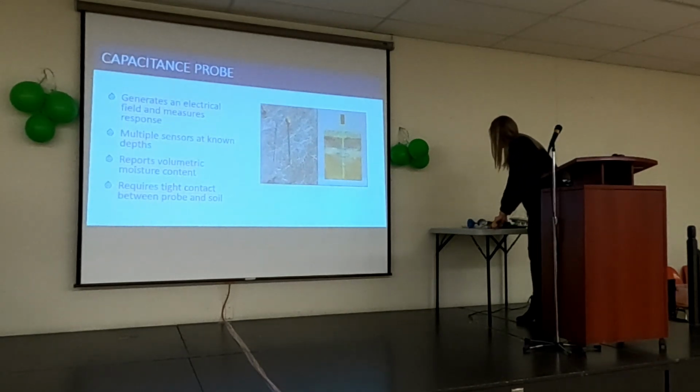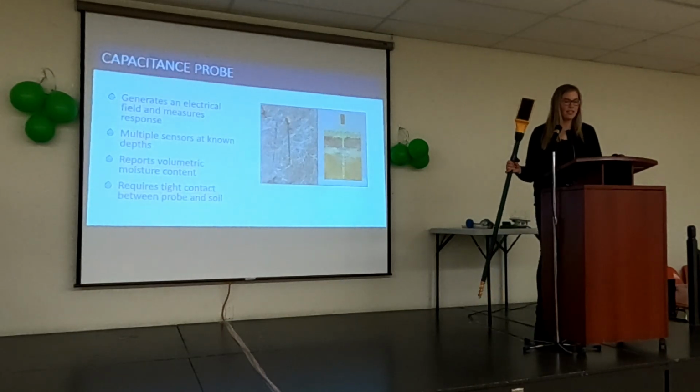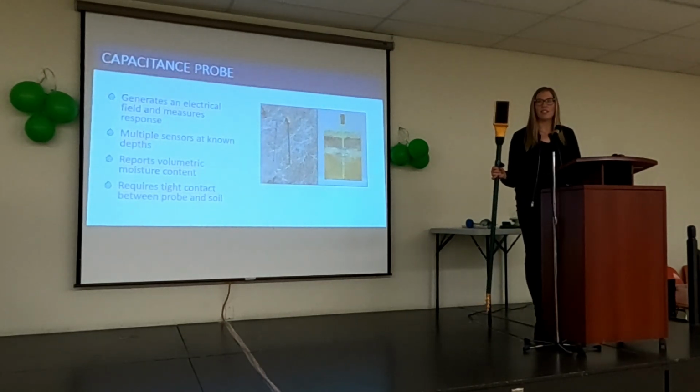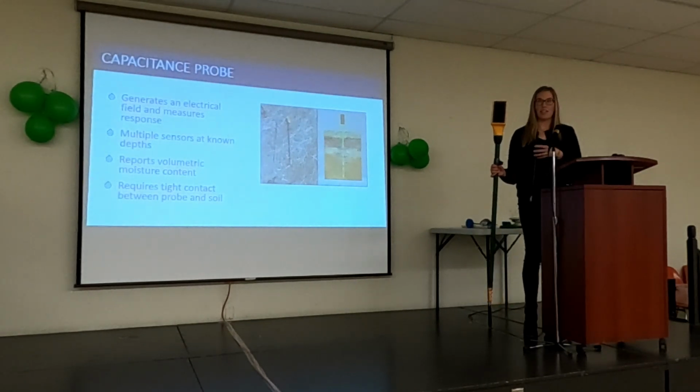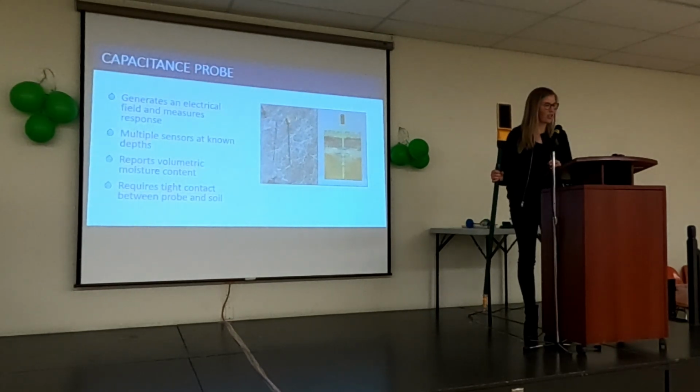Okay, so the next probe I wanted to show was the capacitance probe. So this also uses the dielectric constants to measure soil moisture, but the probe actually creates an electric field, and then the dielectric constants are measured in that field, so it's called frequency domain reflectometry.